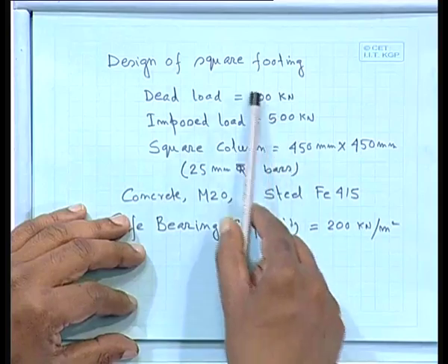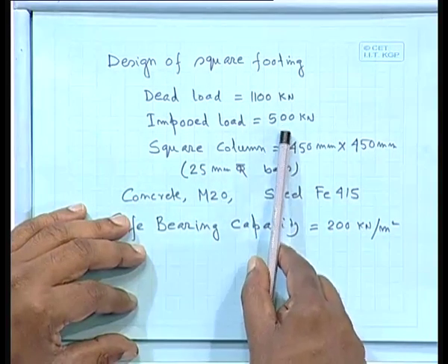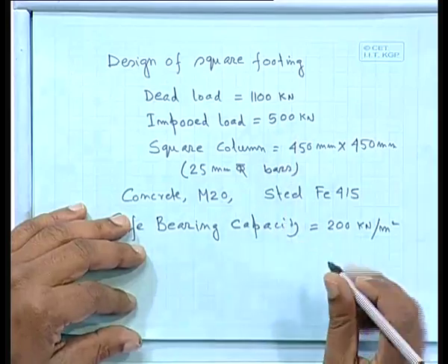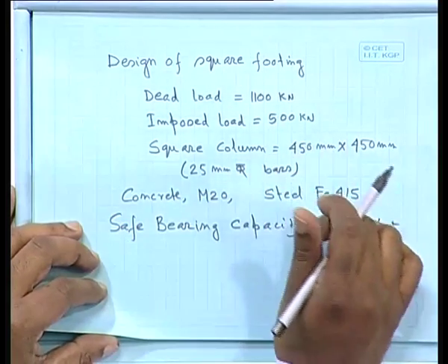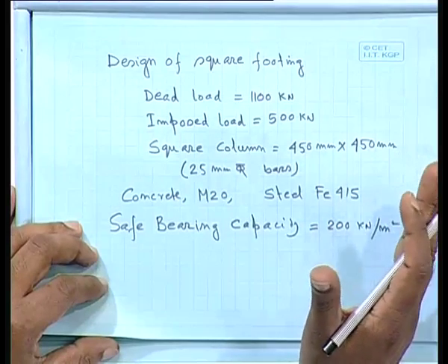But if it is more, maybe 100 meter, then you will find that the vehicle load is very small compared to the dead load. If it is 50-50, we can say it is economic or optimum, but in most cases it is not at all possible to make it economic. In this case, finally, the dead load to live load ratio is almost 2:1. On the basis of that, one can estimate the cost and other things also.